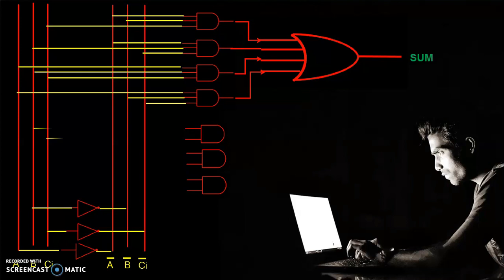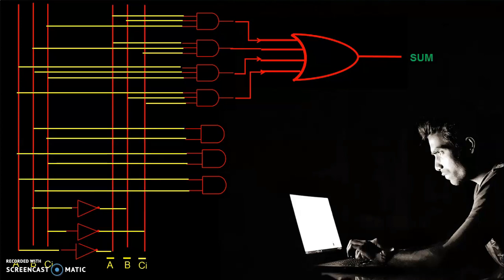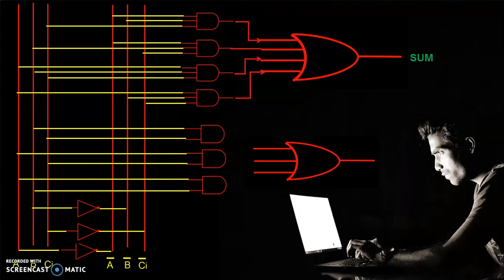So as per the Boolean function, we give input, and as the Boolean function is in SOP form, at the end stage we have to use one OR gate. Because we have 3 product terms, we have used an OR gate with 3 inputs, and the output of the AND gates will be connected as an input to the OR gate, and the output of the OR gate will be the final carry. So this way, with the help of basic gates, we can implement the logic circuit based on the Boolean function we have derived from the K-map.